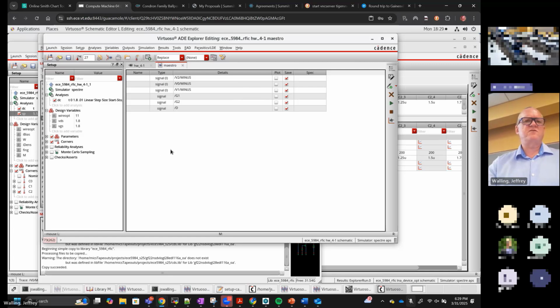Now the homework is going to go through and have you calculate what you're going to end up needing to find the maximum current, maximum drain current. So you're going to need to keep increasing the size of the device until the device can provide enough current for you to achieve the output power that you're looking for.